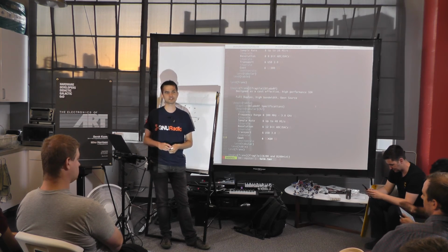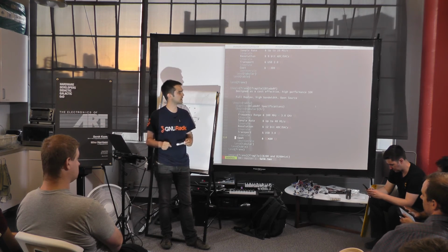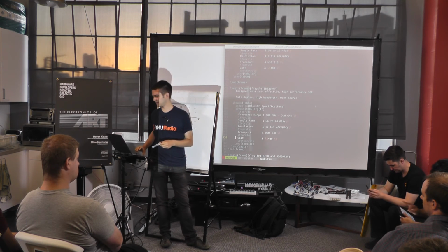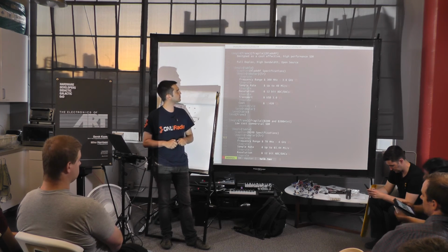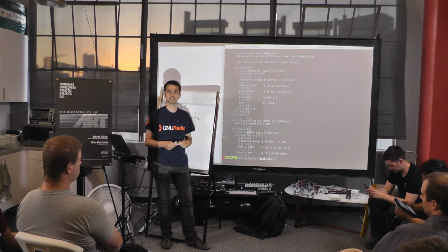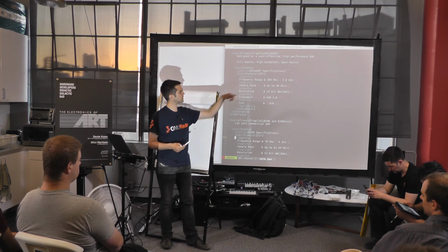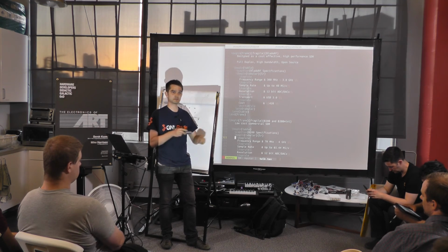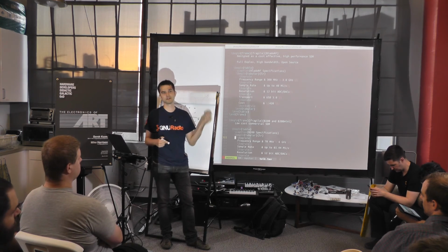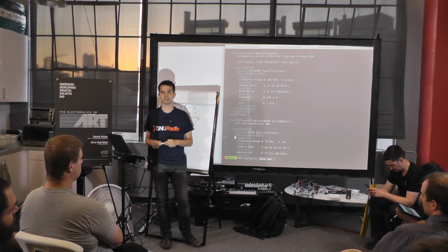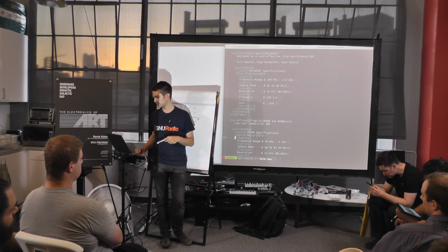There's the LimeSDR, which is coming out sometime quite soon, which is about $250, and has 2 channels, but we don't know a lot about its software support in practice yet. The BladeRF has been out for a few years. It's a full open hardware design, so you can download the full schematics, and I think even the Gerbers for it. 300 megahertz to 3.8 gigahertz, 40 megasamples per second, so we've doubled our bandwidth again. 12-bit ADCs and DACs, fantastic, but the price has gone up again to $420. These all have GNU Radio support, which was one of my criteria for having it on the list.